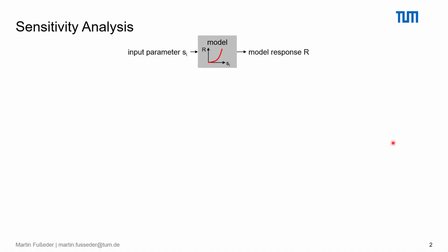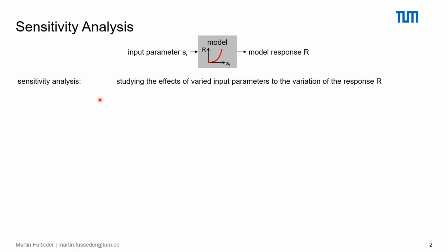Let's start with the question what sensitivity analysis is. Typically we deal with a model, which can be a structural analysis model, with input parameters like stiffness or load parameters or geometrical properties. These are connected by the model with model responses like displacements or stresses, for instance. In sensitivity analysis, we study the effects of varied input parameters on the variation of the response.